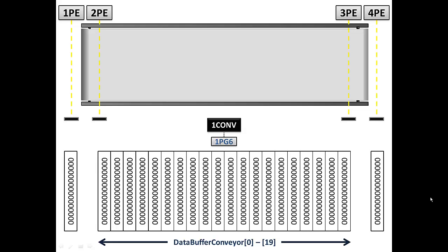Okay, let's take a closer look at the middle conveyor, the buffer conveyor. Now remember, I explained to you that we had a pulse generator that would put out a pulse every so many inches of travel of the belt. It's really generating pulses based on the angle of the drive roller, but we've mathematically correlated that to so many inches of surface travel of the conveyor.